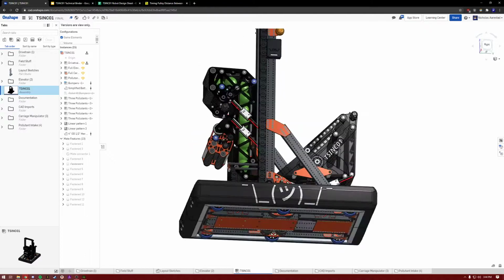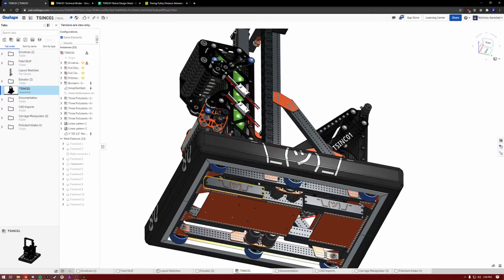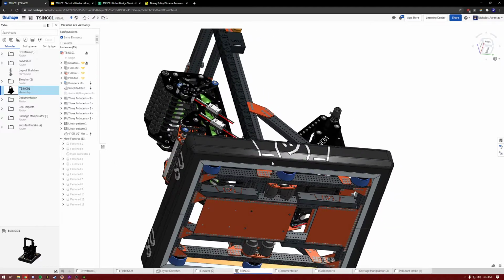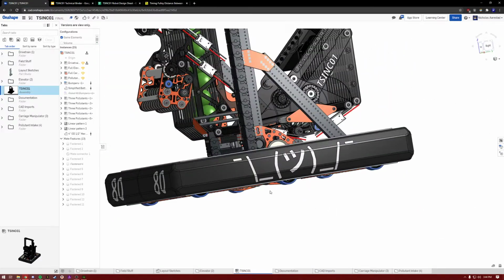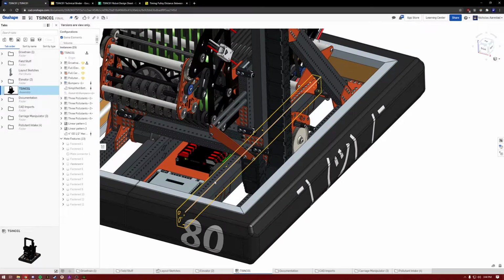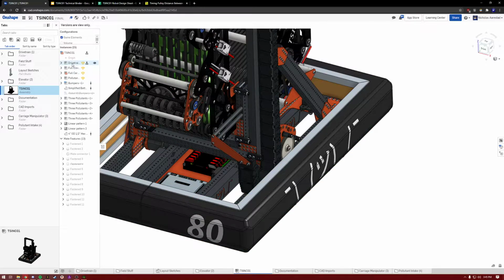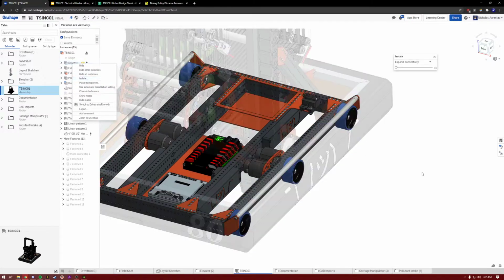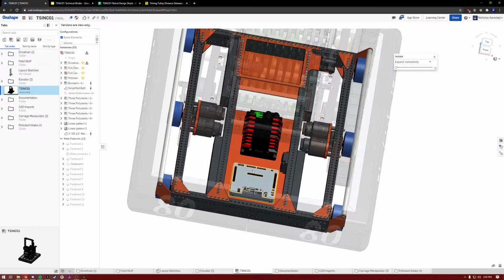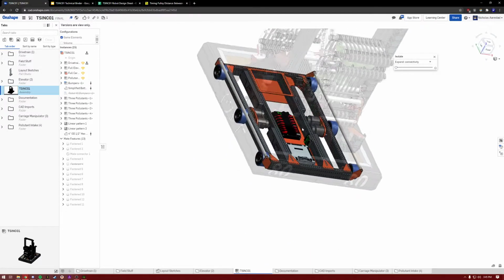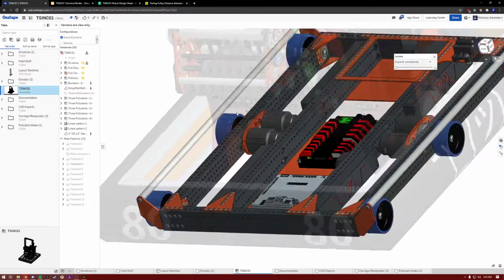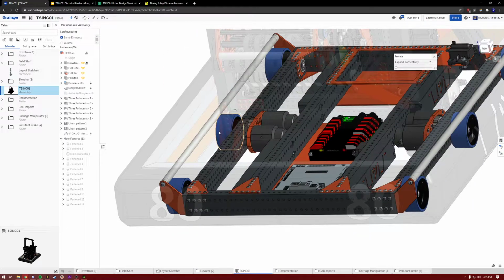So big parts of that informed this design. We'll talk about this drivetrain first. This drivetrain is the four rail architecture that has been becoming a lot more popular in recent years. It's designed to have a battery back here. We've got some single speed gearboxes and some 3.25-inch wheels. In the vast majority of FRC games, wheels this small are a bad idea, but this is a true flat field game, which means that that is acceptable.